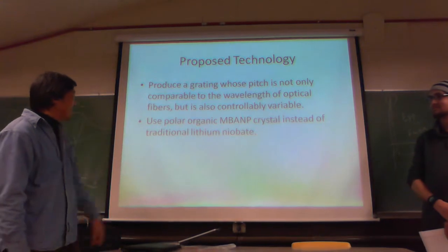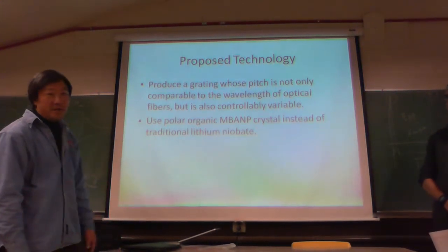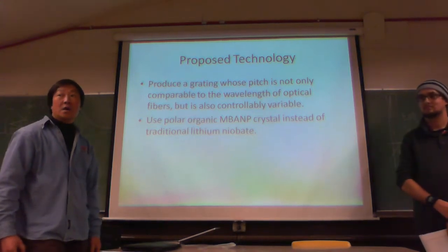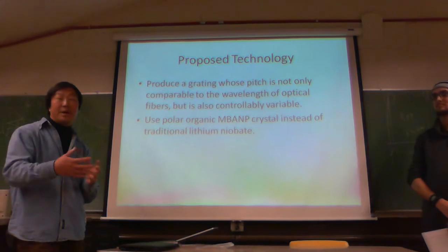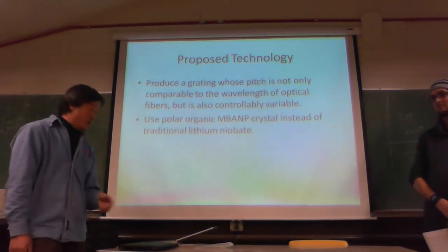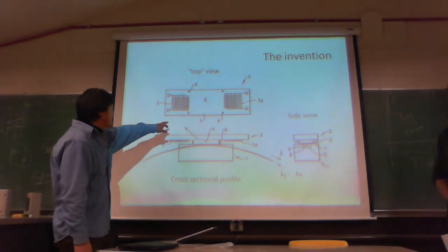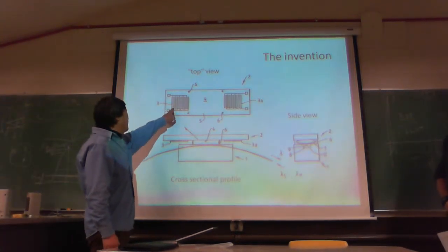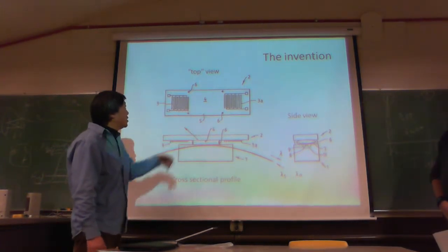They claimed it to be an improvement over the traditional lithium niobate, which is used for piezoelectric crystals. Basically, it's like quartz. And as Dan was talking about, the fingers on these are stenciled onto the crystal.